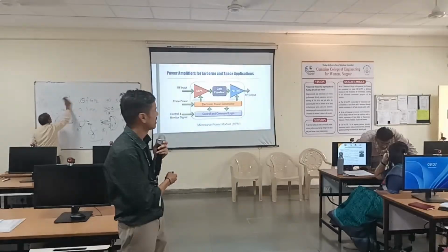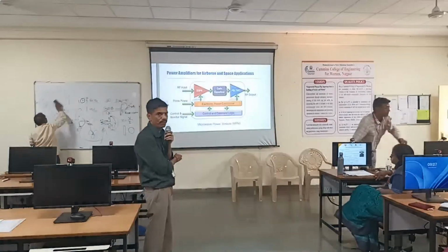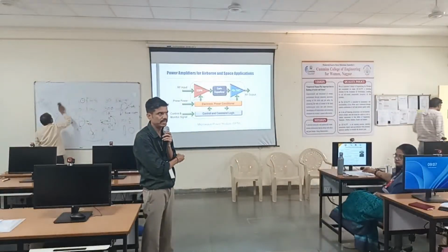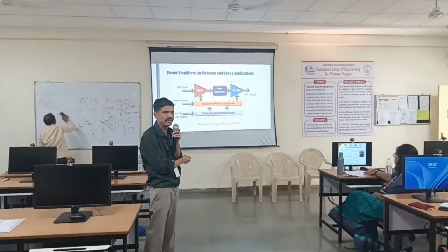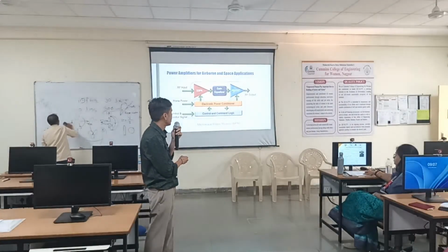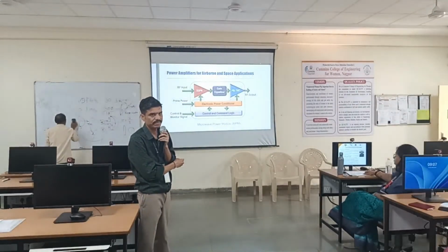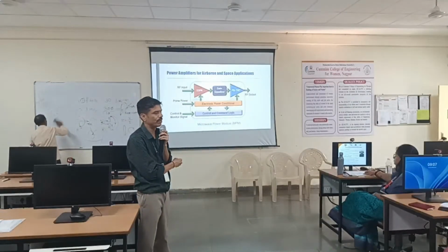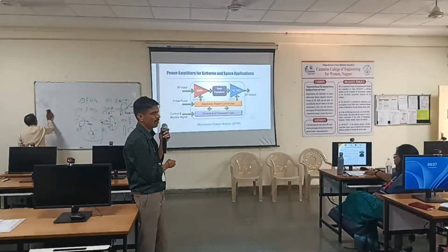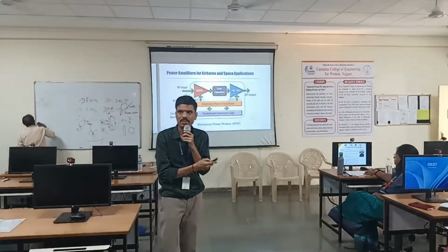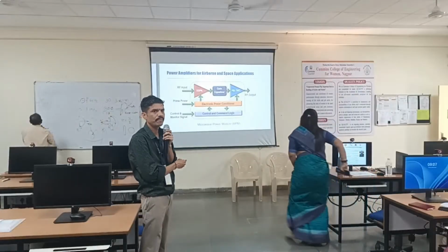So these are the typical microwave power modules wherein we use a few stages of SSPAs, that means solid state power amplifiers. Then we have gain equalizers to stabilize the gain throughout the different PA blocks. And then we have the main power amplifier, which is the TWTA, power booster or traveling wave tube amplifier. Then we have power conditioners and control and command logics to switch on the transistor or some other components. So this is the typical block diagram of any microwave power module we use in defense applications.